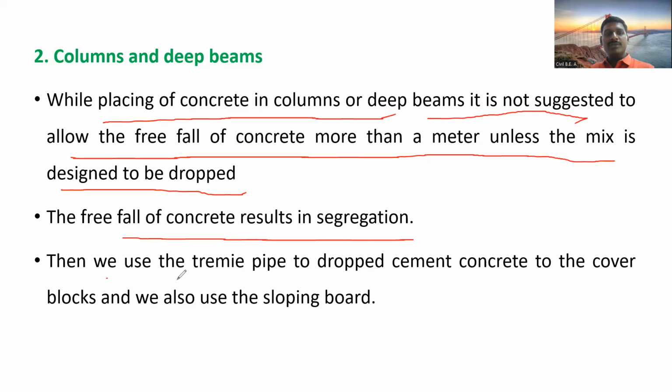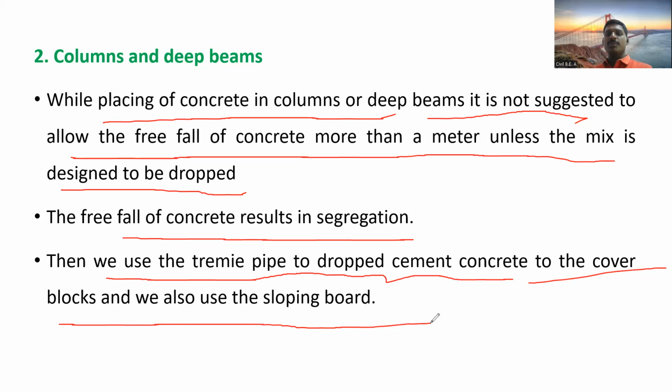Then again, we use the tremie pipe to drop cement concrete to cover the blocks, and we also use sloping boards. So this tremie pipe is also used to drop the concrete, and sloping boards are also used.